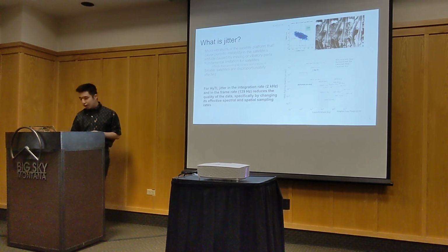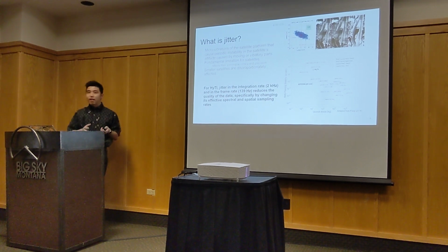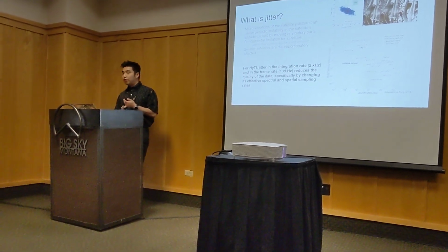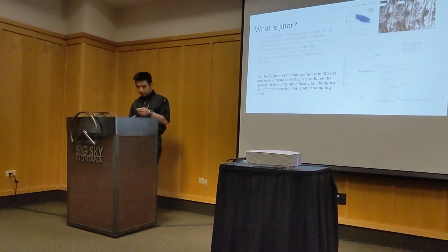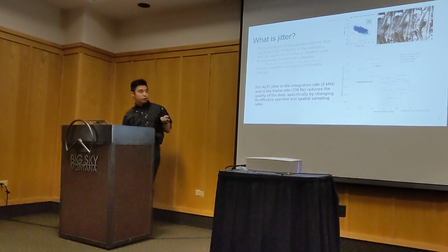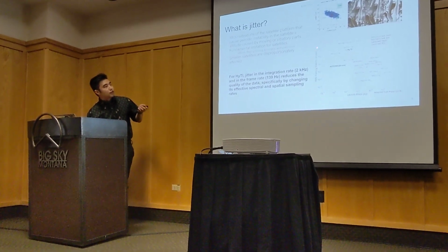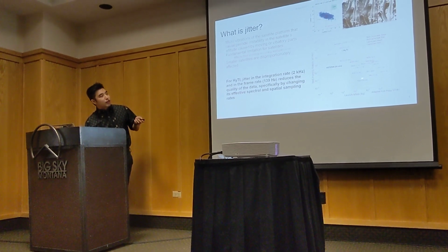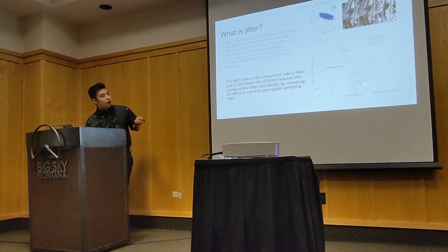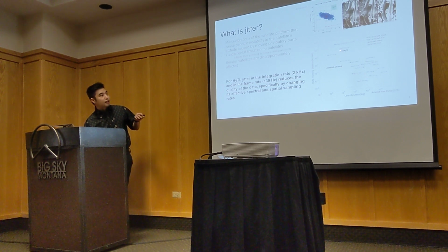But smaller satellites are actually disproportionately more affected, and this is because these vibrating parts, like the cryocoolers and the attitude control systems, make up a larger percentage of their mass when compared to larger satellites. And that's shown here in this figure, where we have launch mass down here and RMS pointing stability here. And here you have missions like Kepler, James Webb, and Hubble. Very high launch mass, very exquisite pointing stability. And as you move down in launch mass, you can see a more modest ability to point. And HyTI sits, given its requirements, about right here.